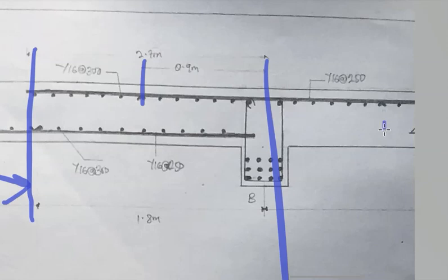As you can see, the curtailment here, from the center of the support, is at least 0.1 times the basic length. Our basic length here, remember, is 9 meters, so 0.1 of 9 meters is 0.9. Hope you got it. That's where our complete area of reinforcement lies. Then anything you want to extend after that, you are going to use half of the reinforcement, meaning you are going to increase the spacing. But remember, again, the spacing shouldn't exceed 300 mm. So that's why I use Y16 at 300 mm here.